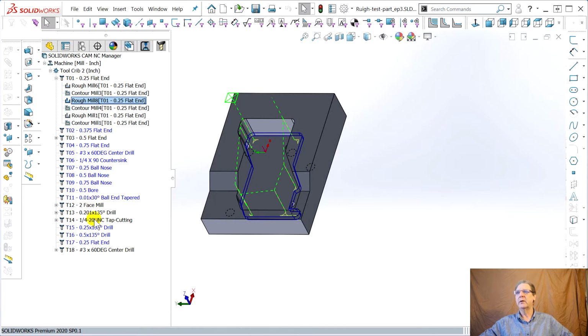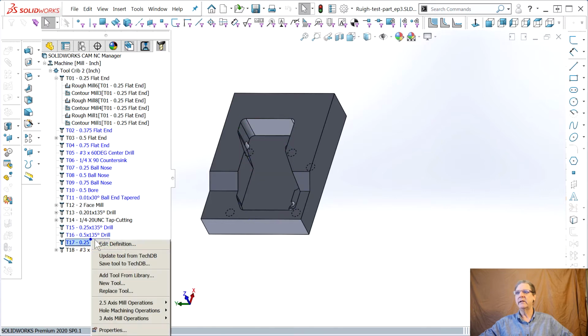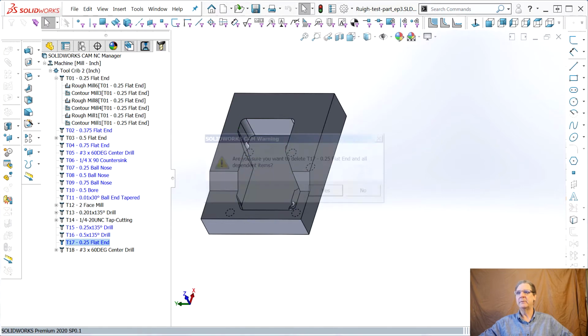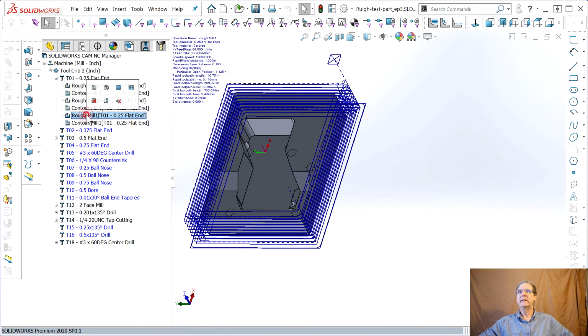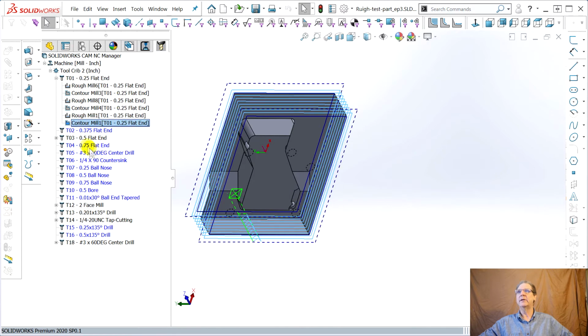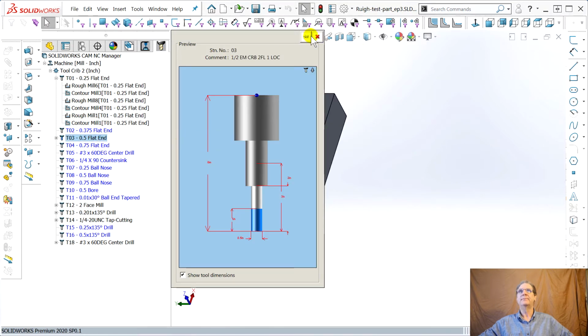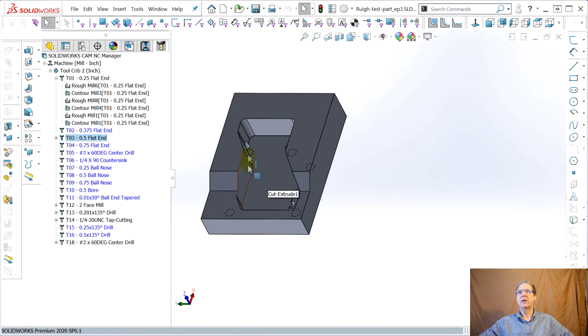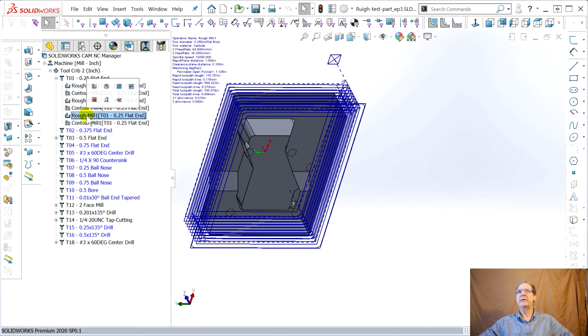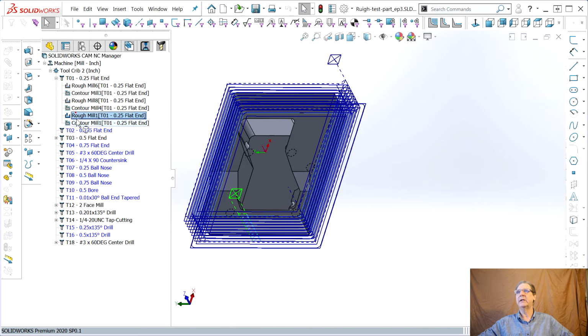Where'd the first one go? Did it disappear? Tool 17, right? There it is. Pretty sad you've got to remember stuff by numbers. All right. So there we are. Now, let's look at this out and this out. Well, they're using this flat one to hog the quick rough machining on the inside. So rather than doing a 1/4 inch here and here, there's less tool deflection, less problems.